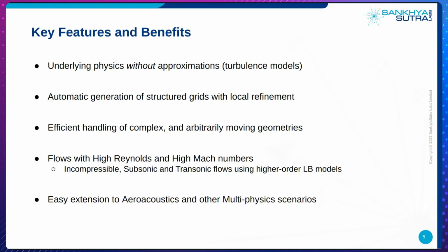The key features and benefits of the solver, as I already spoke in the previous slide, are that we solve for the underlying physics without any approximations. We don't discretize the Navier-Stokes equation and introduce modeling in order to arrive at the solution, but we essentially solve the Boltzmann equation, which stems from the kinetic theory of gases, and we get the exact solution to arrive at the macroscopic moments that are of interest to the user.